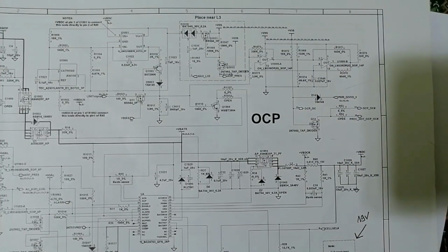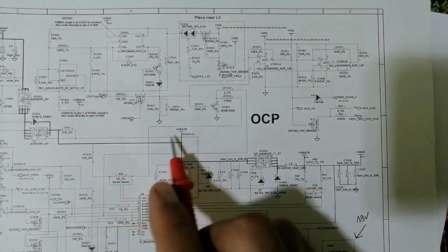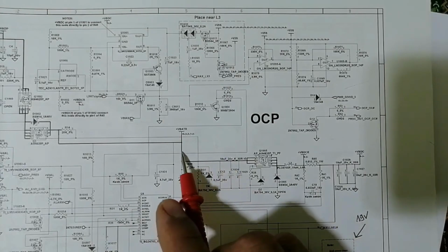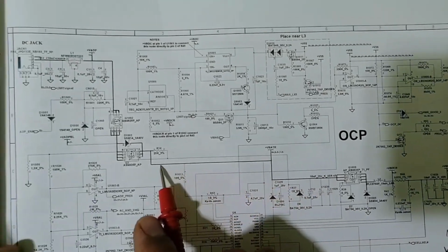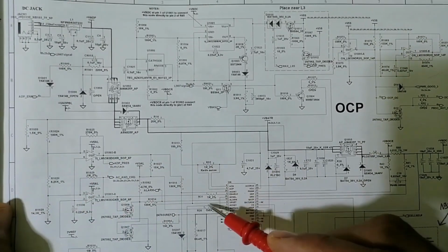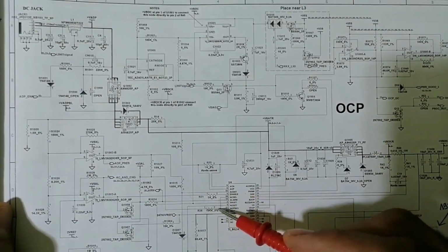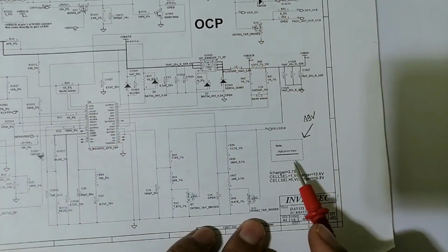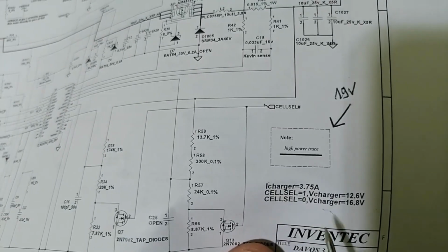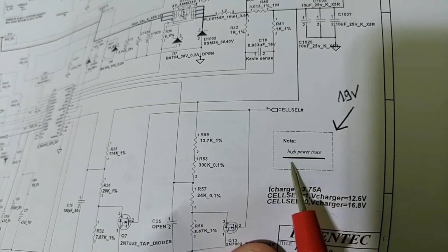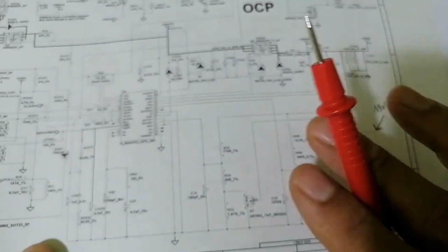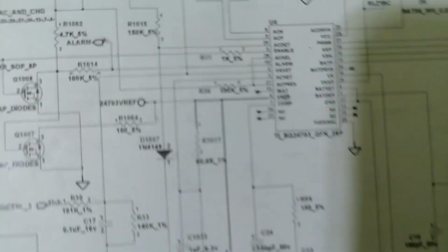Also in the circuit diagram, you will find the same working principle, as you can see. Do you see over here? This is a bolded line. This bolded line basically means we have a high voltage over here. And those lines mean just a signal, a low voltage. If you pay attention here, guys, we have a note in the schematic. Do you see? This line means a high power trace, 19 volts. So let's see an IC, for example. Let's see this IC over here.